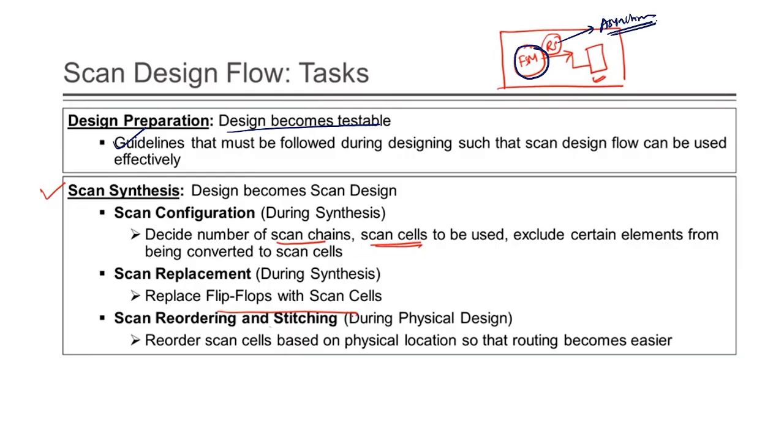You converted this design into a scan chain, so whatever asynchronous reset is there may break. In order to avoid that breaking of the reset, you need to follow this design preparation. That means whatever the design is, it should be testable.